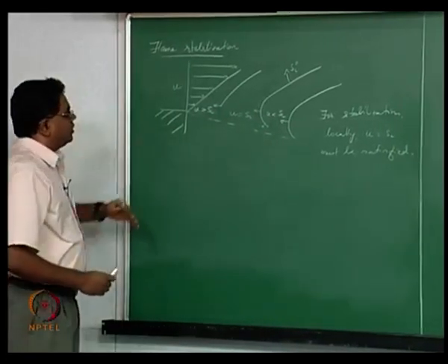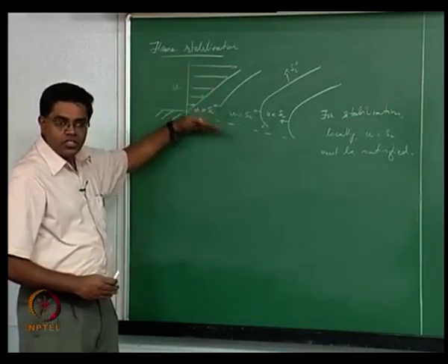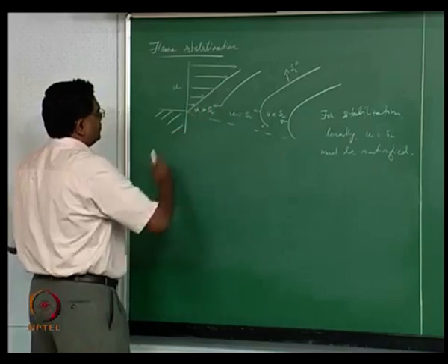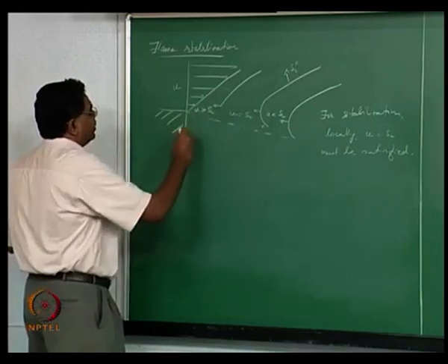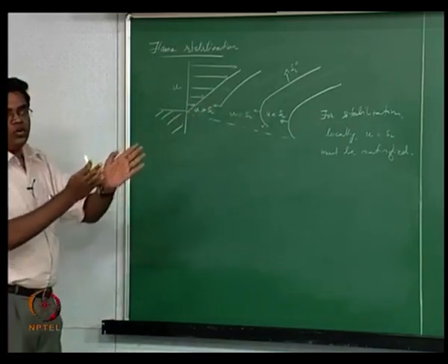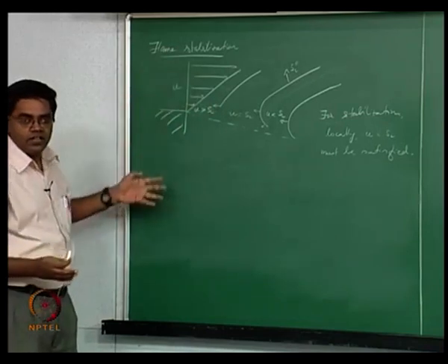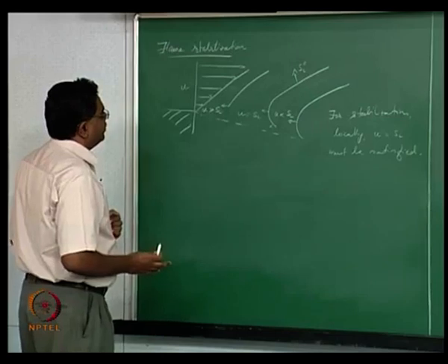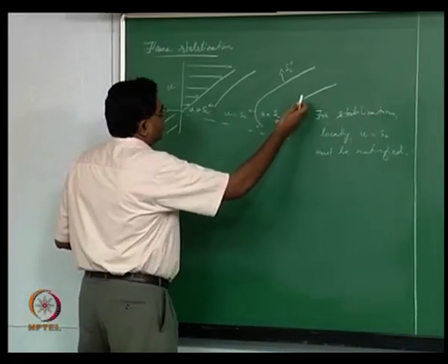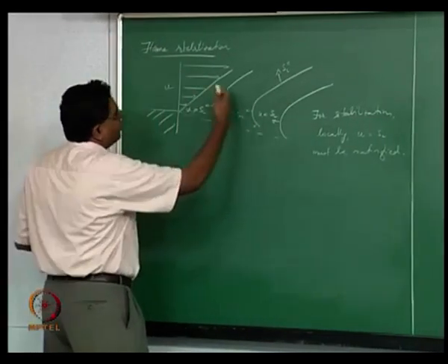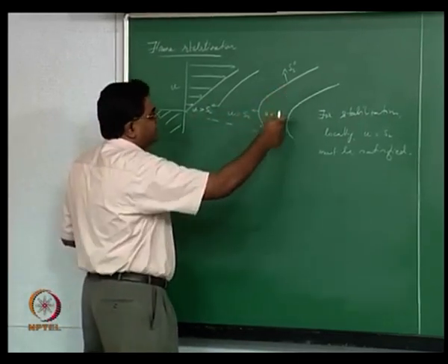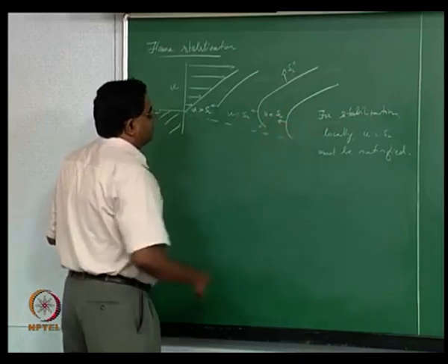The other way to look at it is also the radial direction. As the flame stands closer to the burner, the heat loss is more and the mixing field is quite narrow between the premix reactants and the diluting ambient gas, whereas as you go further out, the premix mixture can go further out into the mixing zone, and the flame can establish itself further and further out.